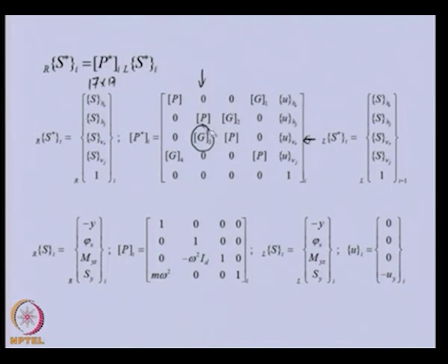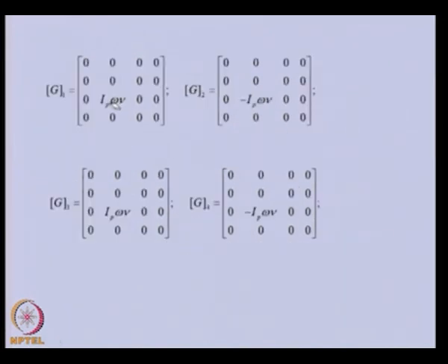And in this particular case, you can see the G is this one, in which omega is the spin speed of the shaft, nu is the whirl frequency, that is the natural frequency of the shaft, and now both whirl frequency and the natural frequencies are appearing. That means natural frequency will now depend upon the spin speed of the shaft, which we already saw in the gyroscopic effect when we discussed that topic in detail. So, we have seen the derivation of the gyroscopic effect, and how the point matrix gets affected by it.